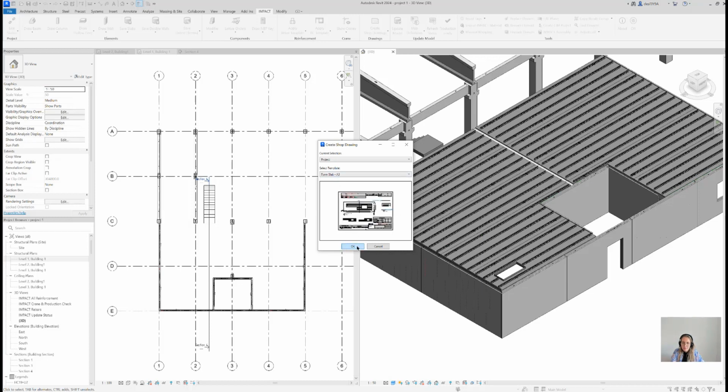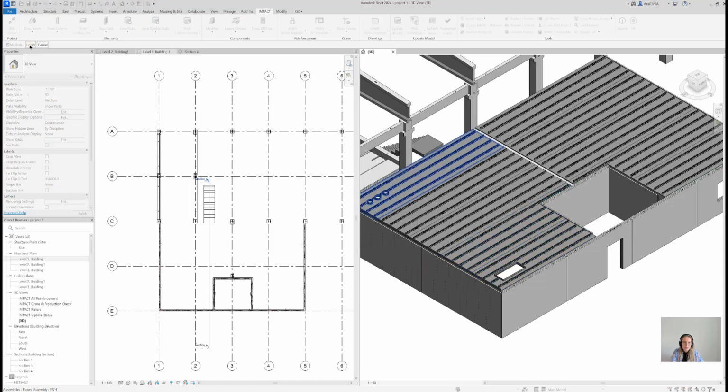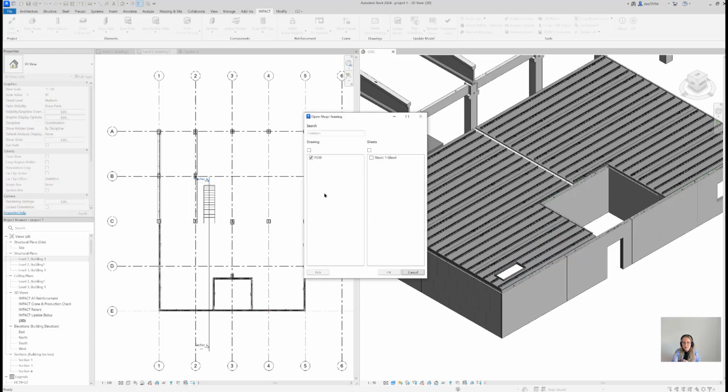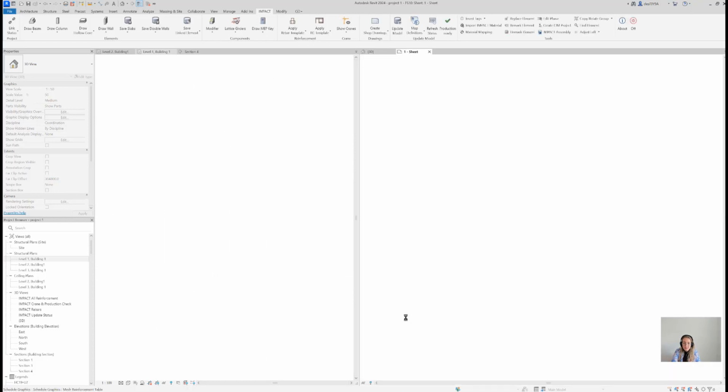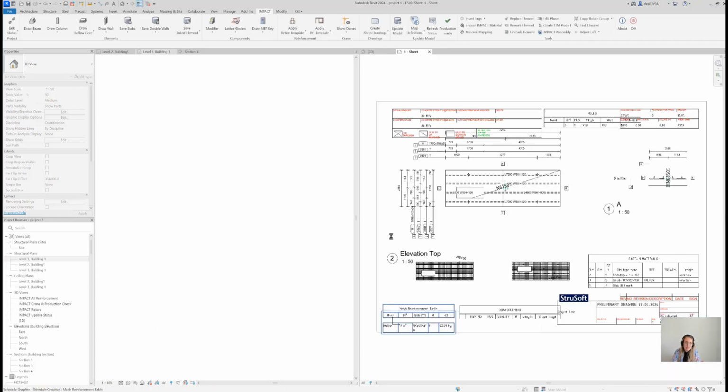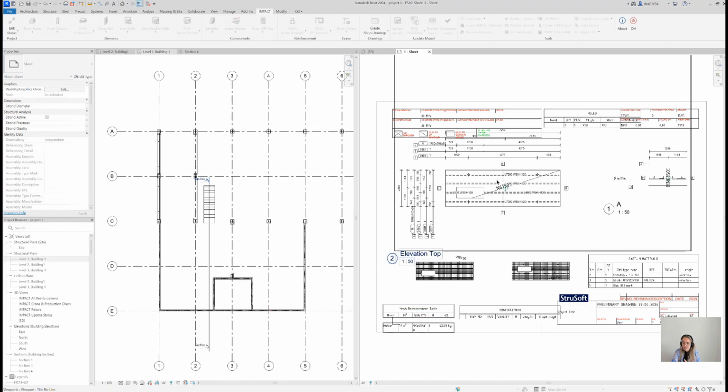You see here, of this element, say finish, and Impact is now automatically creating a production drawing for you out of a predefined template. What is good to remember here is that anytime you make a change to an element, you can always resave it to the Impact database and update the shop drawing. So it's what you get now, but if any changes come on your way to your final design, Impact will be there to help you.